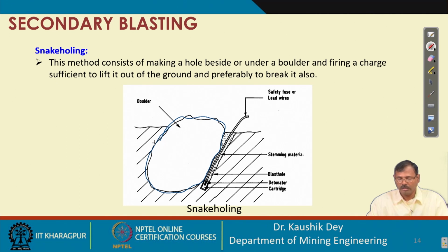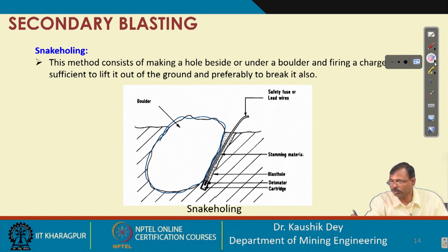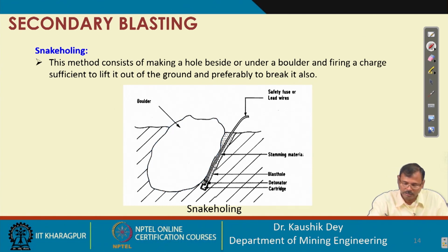In this case, instead of carrying out drilling and blasting in the boulder, one can carry out drilling adjacent to that boulder, and after drilling, an explosive can be placed here and accessories are properly placed, then the stemming is carried out and it is blasted.